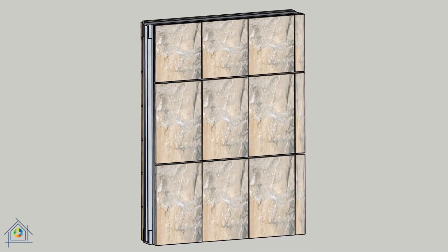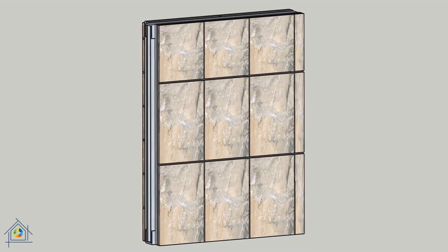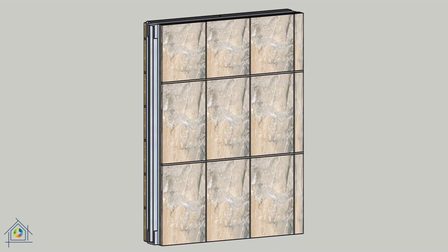To properly connect the stone tiles to the mortar, the back of the stone is restrained with wire or suitable metal pieces. The gap between the stones is filled with cement mortar and stone powder in a volume ratio of 1:6.